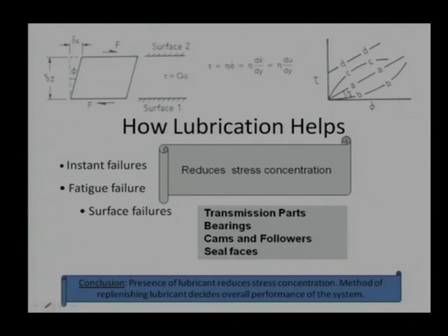So, we can conclude from this slide that the presence of lubricant reduces the stress concentration factor. That is substantial and it is a very good factor for us. The method of replenishing the lubricant decides the overall performance. It is not only about providing lubricant at one instant, it is a continuous phenomenon, and if the lubricant is wiped out or squeezed out, then we need to again and again bring the lubricant to the interface. So, that is important, and that is why the study of the lubrication mechanism is very essential.